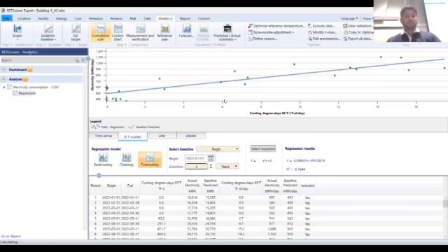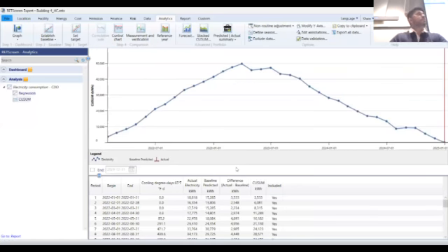So I'm going to click on cumulative sum, and you see this is, instead of comparing every month and every curve, I want to have a moving or a running total of the difference. So if in month one, I have actually used more or less than what I predicted, it's going to be reflected. If I see this chart going up, it just means that I'm not saving energy. The moment it starts going down is when I'm starting to save energy. That's what essentially this chart is showing you.